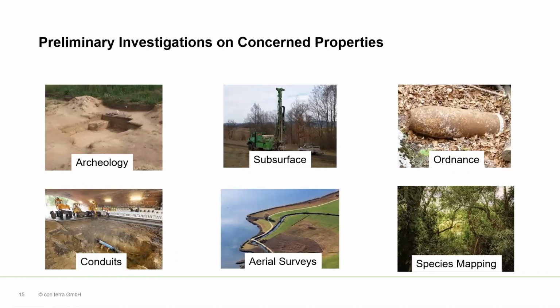Underground or subsurface investigations are used to analyze the local geologic profile and also to determine the thermal conductivity of the ground, which can be an important factor in determining if the site is appropriate for building the power line or not. Then we also need to investigate if there are any unexploded ordnances from World War II left in the ground. We can use aerial images to find out if any bombs have fallen to the ground and not exploded, and then of course these ordnances need to be removed.